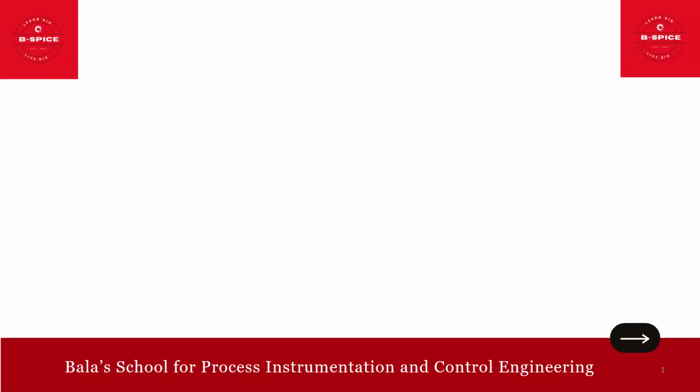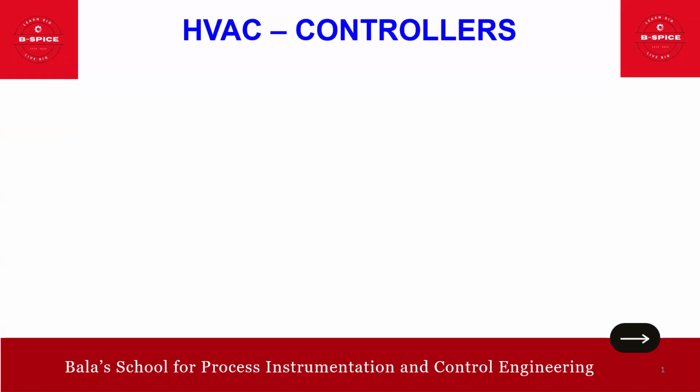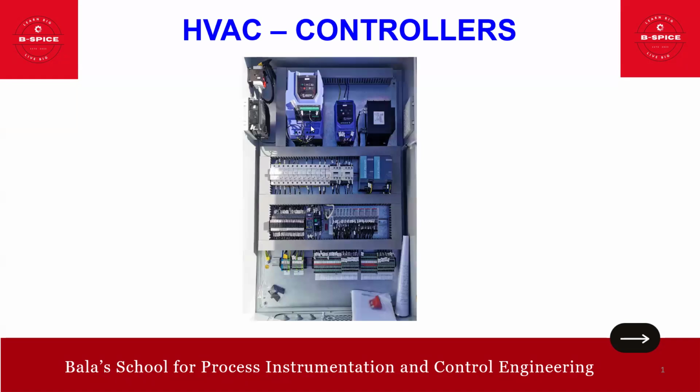In this session, we'll continue with HVAC, wherein we'll focus on controllers. This is the look and feel of the controller. Of course, you would have seen many DCS controllers, but here we are focusing on the HVAC controller. So, controllers in the sense that we are going to talk about controller action, whether direct or reverse action, and how to identify the reverse or direct action based on application, very important and very critical.